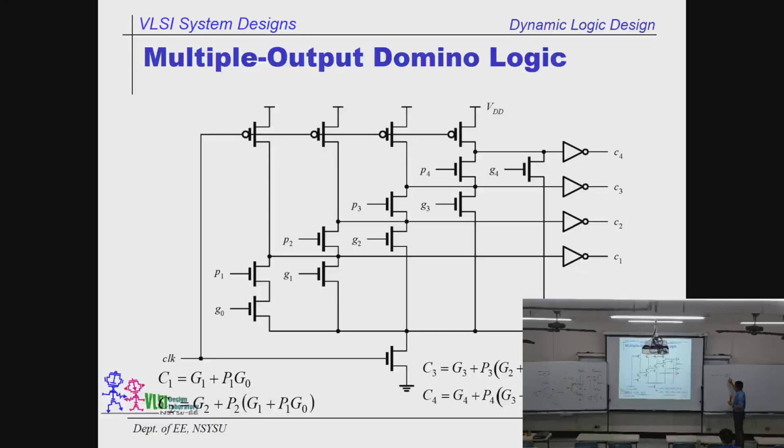And this one gives us a big problem, because if you use a traditional way of adder design, this is A0, B0, and C in. Okay, and the C1 goes over here, and this is sum 0. Again, sum is no issue, but you have a very long delay.